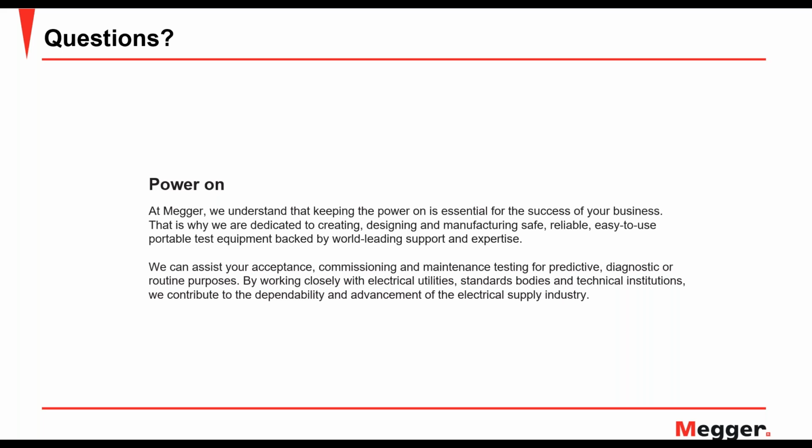So I know at the end of the presentation, and I do realize that some of these questions probably came in before all of the slides were complete, but I know that Sanket mentioned that the range for voltage of Megger's FRAX, that's our SFRA test instrument, went up to 24 volts peak to peak. The default for the instrument is the really traditional widespread one that's adopted. It's 10 volt peak to peak test voltage. So it will default to that, but certainly the user has the ability to change that test voltage if needed, particularly if you're trying to import some other SFRA traces that perhaps were performed at different voltages.